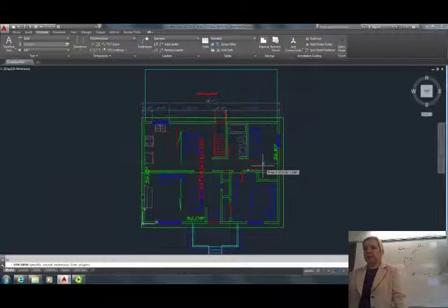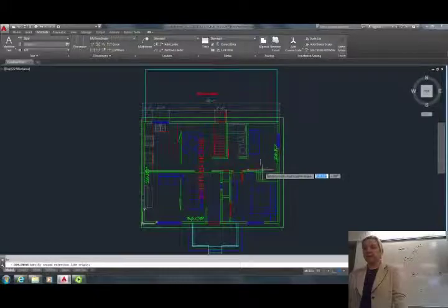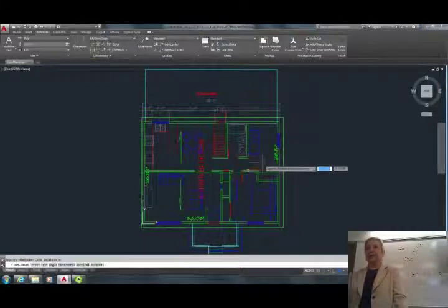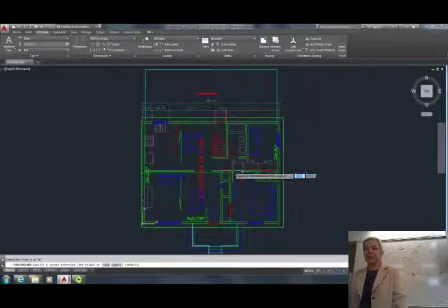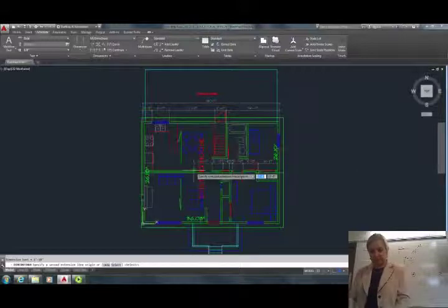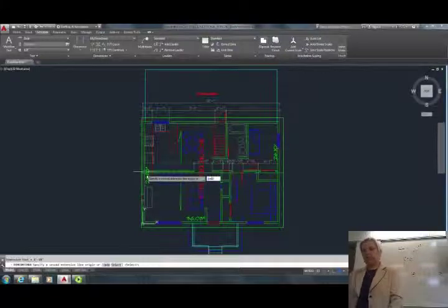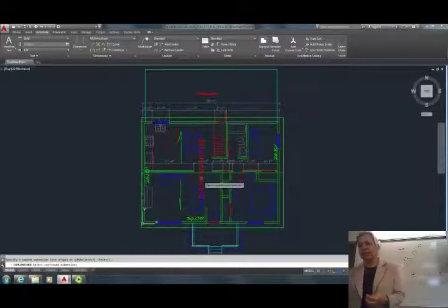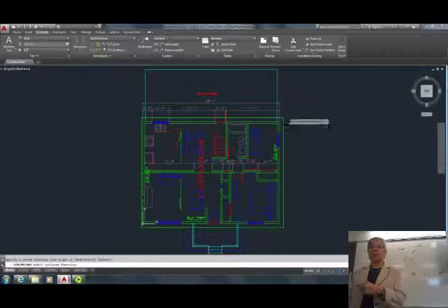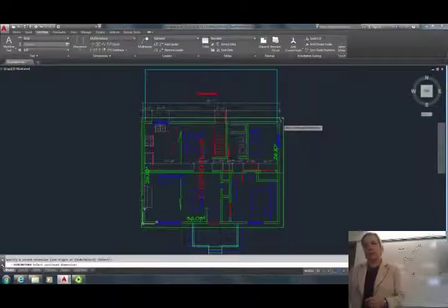But I'm working with the existing file, so let's say I'm going to be building this closet, but I don't really care about the closet opening. I care about where that wall is to be built, and then the third point is the location, and then you would click on continue. And do get into the habit of zooming out closer and getting the correct corner, and then I would say perpendicular to finish the string. So you should be zooming in and out to make sure that you're catching the right corners. If you don't do that, sometimes you could be catching the extension lines, not the corner, but the extension line of your dimension line, and you could be in trouble.